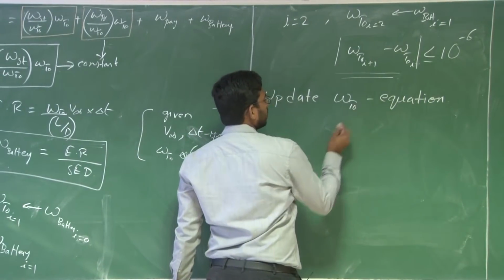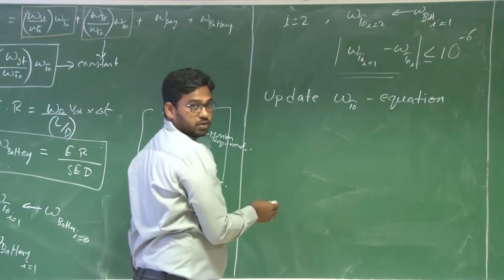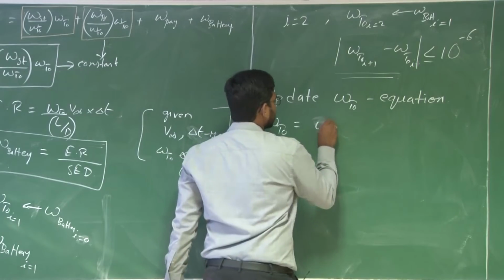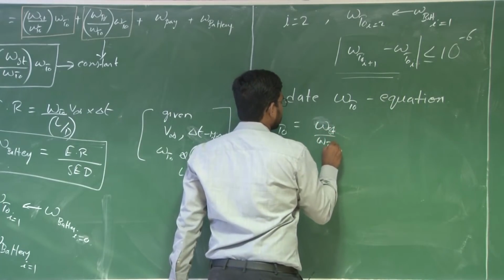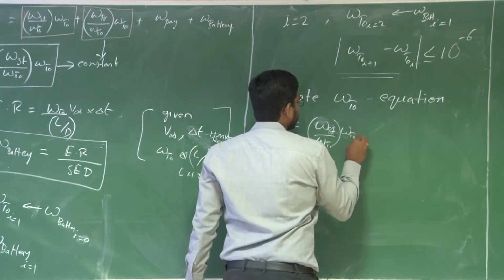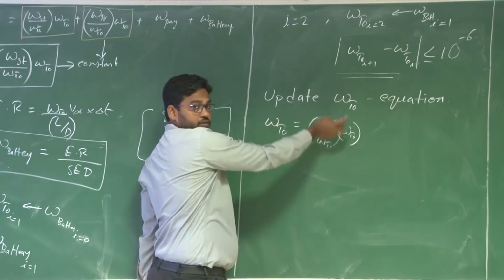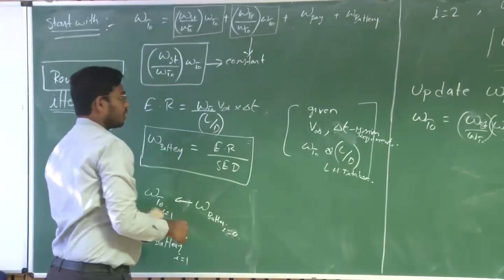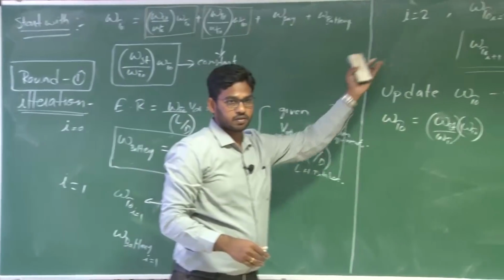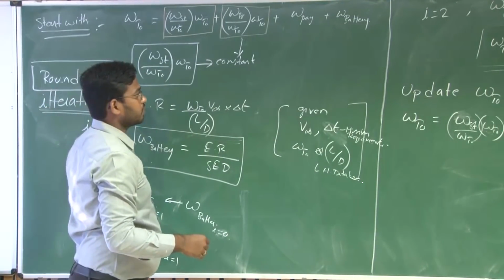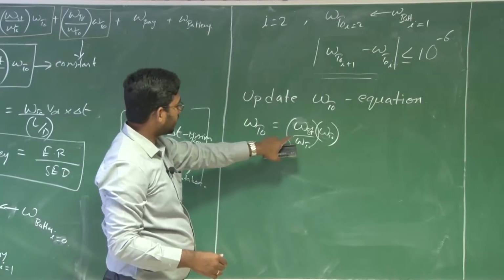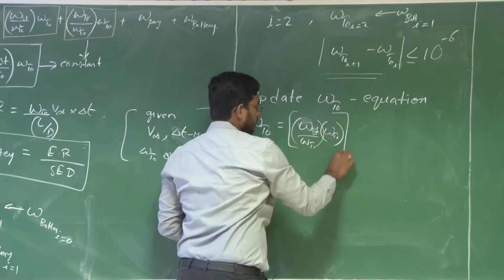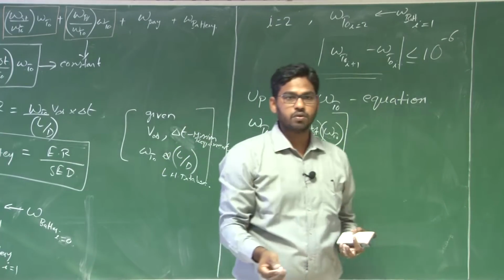Now you have the updated WTO, right? Why? Because W takeoff is equal to, say, W structure, which is again a ratio. This is updated from here. At the end of this first round of the iterative process, there can be n number of iterations in this first round. By the end of this first round, you will get a particular takeoff weight. Update that takeoff weight here with the same structural ratio. That means this structural weight is also updated as per your new mission requirements.